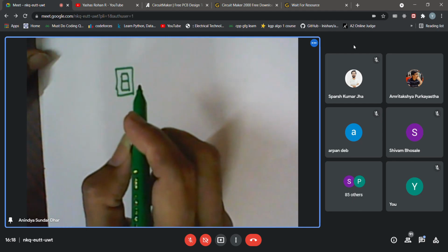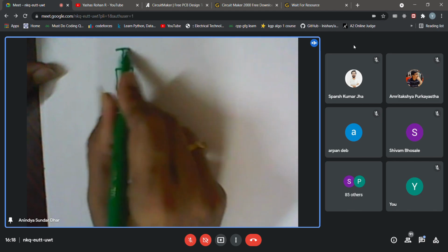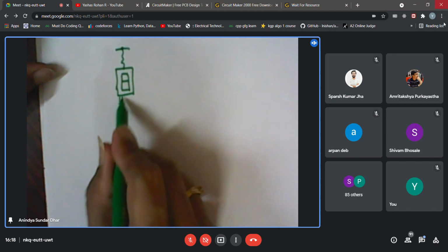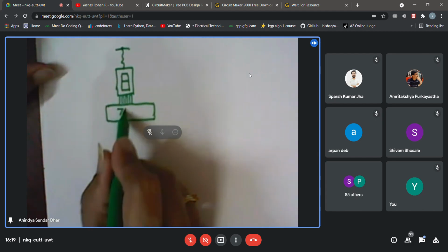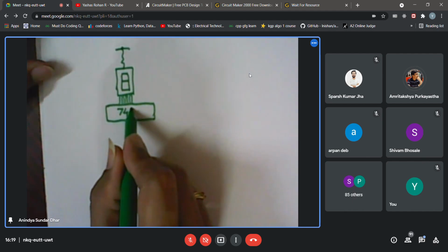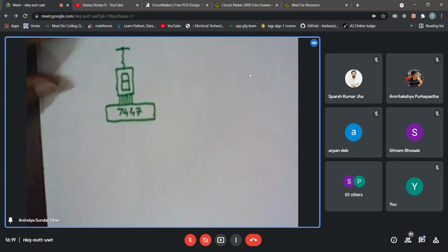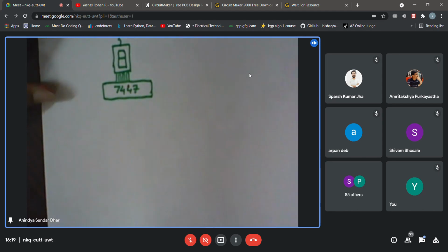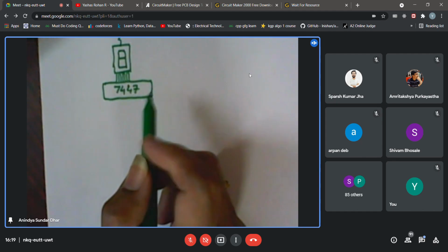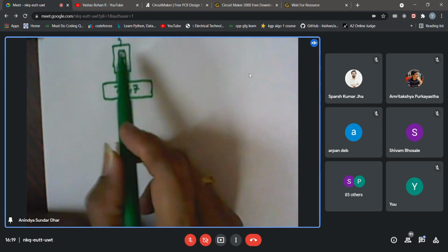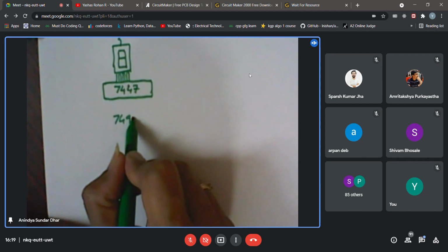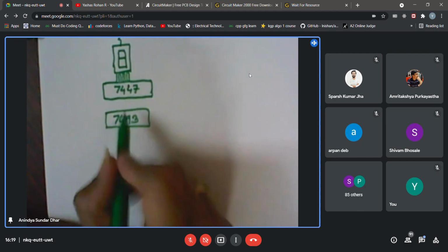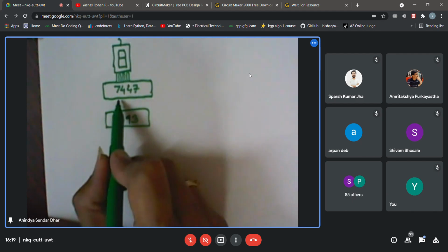Hello? Yes, sir. Okay. So, I am having a 7-segment display over here and 7 connections going from, by this time you remembered the chip numbers. What is the chip number? 74? 47. Okay. 7446 is also there. That is, I think, having a little less current driving capability. Not actually current driving capability, that is a different voltage also. Anyway, 7490 or 93. I'm writing 93. How many connections would go from 93 to 7447? Tell me. 4. Okay.